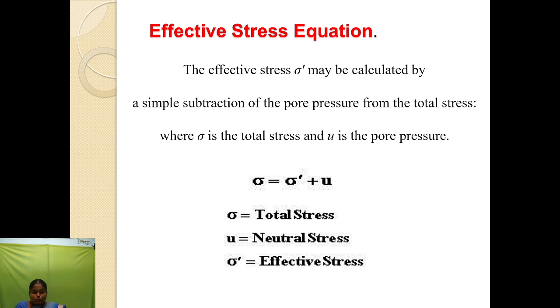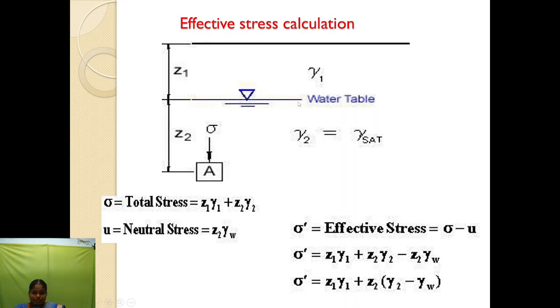And neutral pressure is the pressure transmitted to the pore fluid, which is equal to the water pressure per unit area above the plane. It does not have any measurable influence on the voids ratio, shear resistance and other properties of soil. Thus it is named neutral pressure.